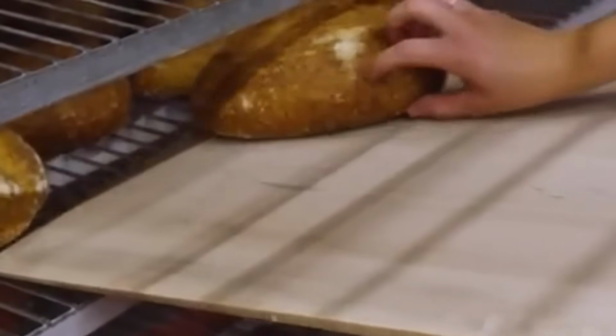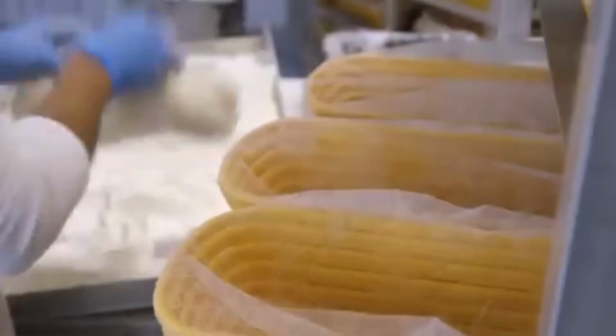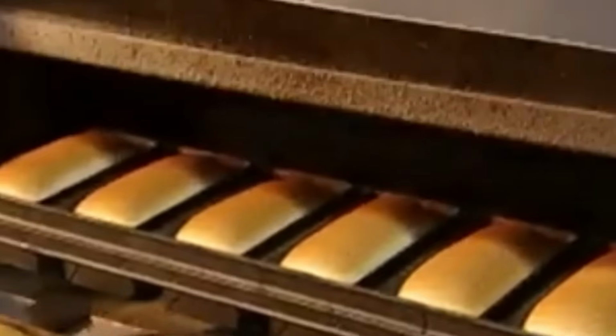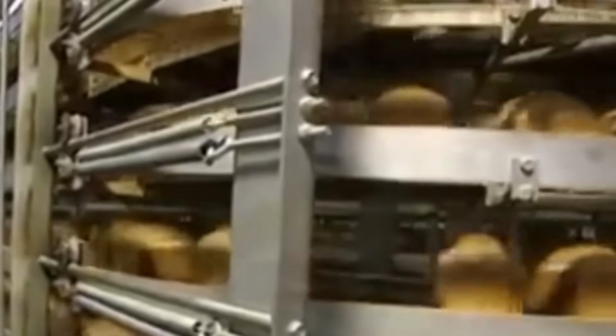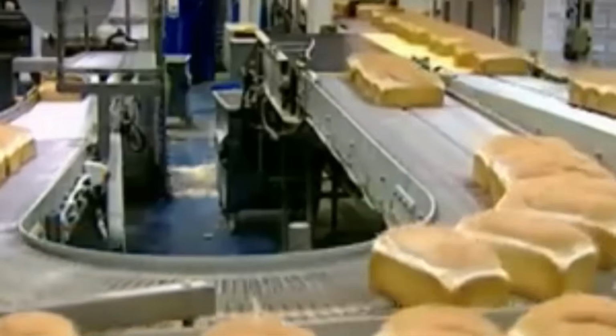A rotating arm, fitted with suction cups, lifts each loaf upward with precision timing, placing it onto a transfer belt while the empty pan continues onto a cleaning line. The pans are scrubbed with mechanical brushes, sprayed with sanitizer, and then dried by air knives before being stacked or returned to the molder for the next round. Meanwhile, the bare loaves now advance towards slicing and packaging.